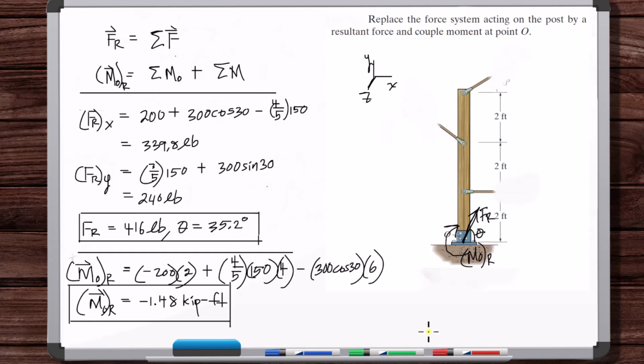And again, don't get bogged down thinking, oh, well, we couldn't actually apply these forces in real life, like come here with some twisting machine and a winch, and it would be the exact same. Yeah, because the deformations right in the regions where the load is applied would be different. But it's not like that. We're thinking about this as a rigid body, and we're just doing a static analysis. If you applied the forces here, the local deformations would be much different than if you had forces applied here. But we're not looking at local deformations. We're in statics, dynamics, rigid body mechanics.